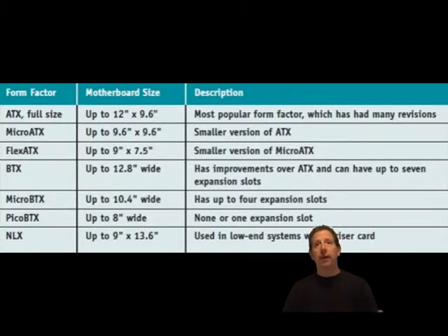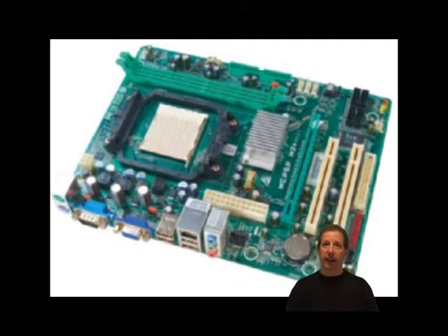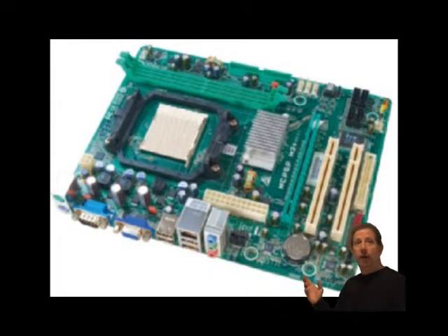It is a major variation of ATX and addresses some technologies that have emerged since the original development of ATX. It reduces the total cost of the system by reducing the number of expansion slots on the board, reducing the power supply to the board, and allowing for a smaller case size. The micro ATX motherboard will fit into a case that follows the ATX 2.1 or higher standard.